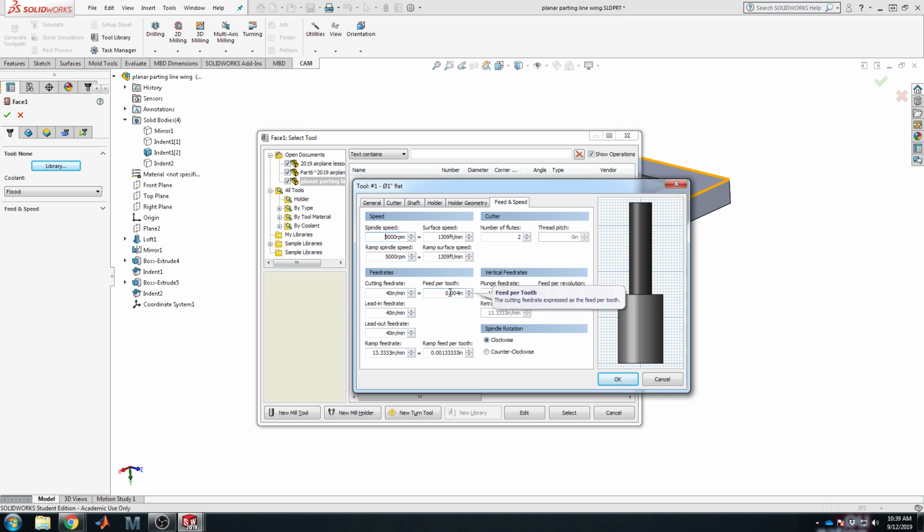It's actually just a router, a handheld router head, and it's a simple part. It's a cheap part, so that way, if while learning, if you make a mistake, it's not going to cost us a ton of money to fix. Cutting feed rate, extremely, extremely important number to set. Our machine really should never go above 50 inches per minute.